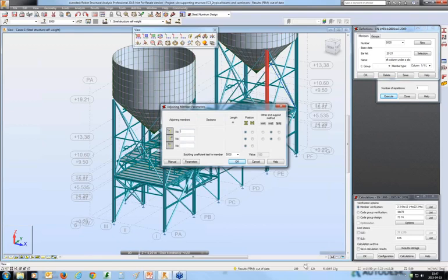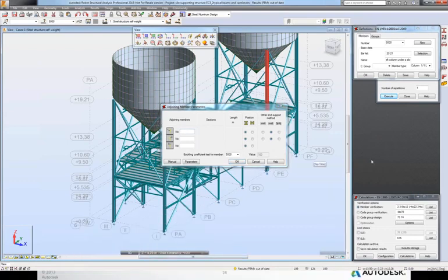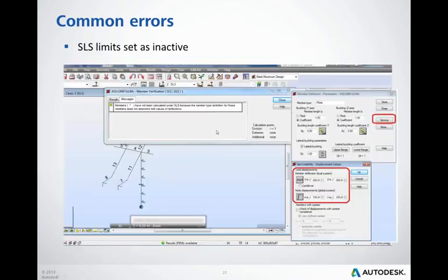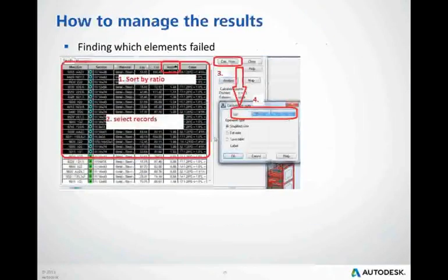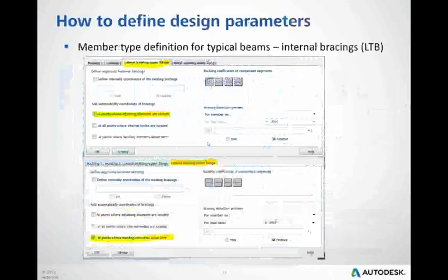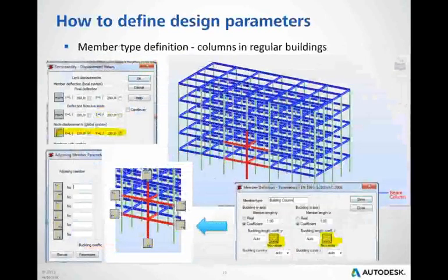This is what is done automatically. So let me go back to my PowerPoint. If I go back to one of the slides, there was quite a nice picture of that. You can see this is the automatic detection of the buckling of the adjoining elements for this middle column here.